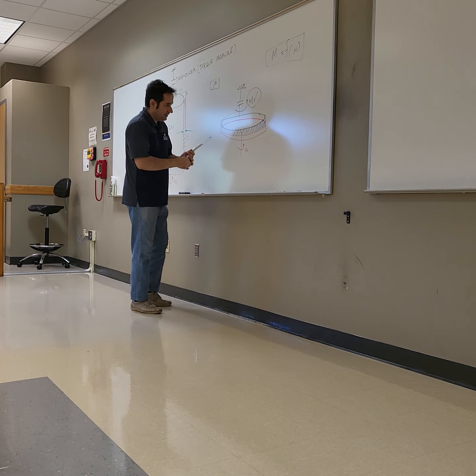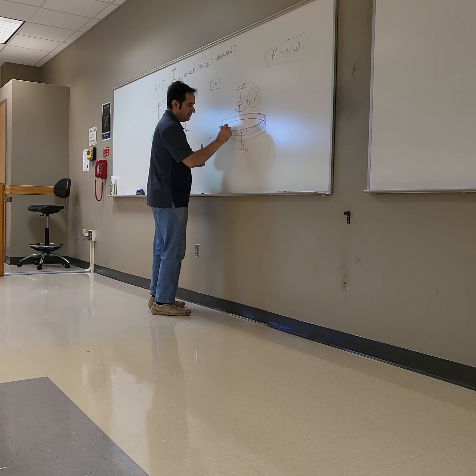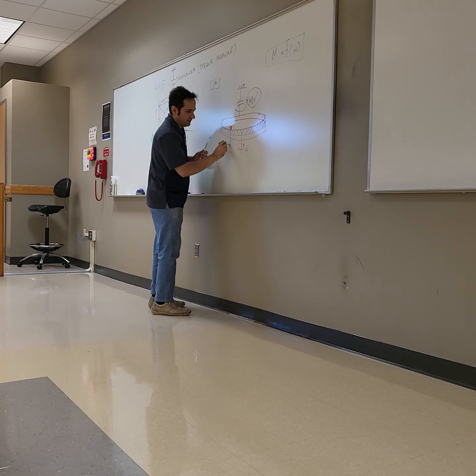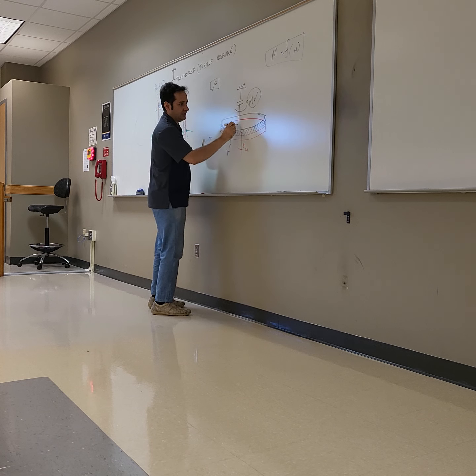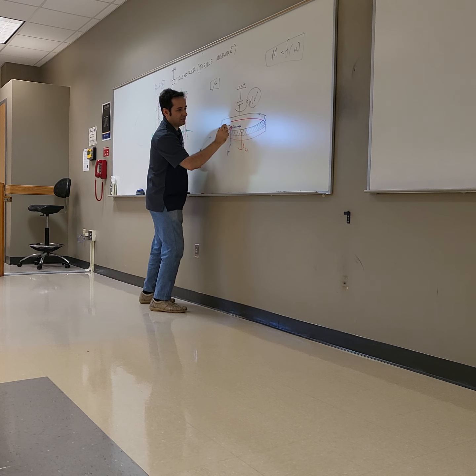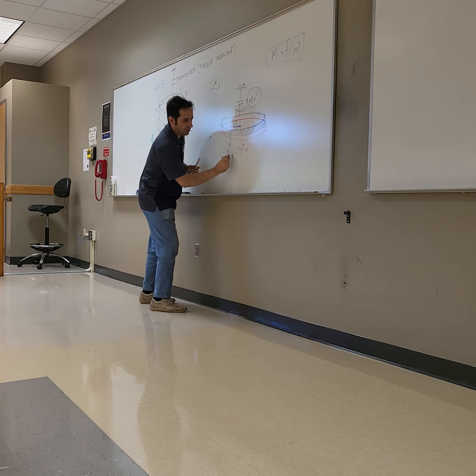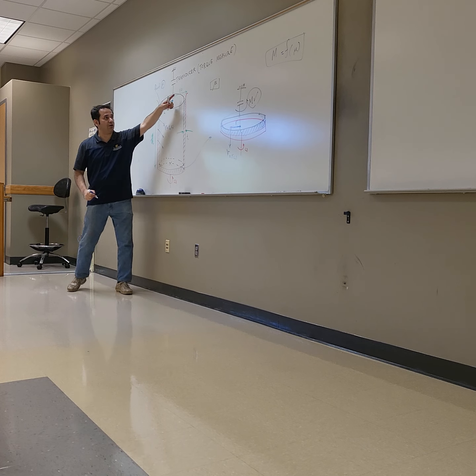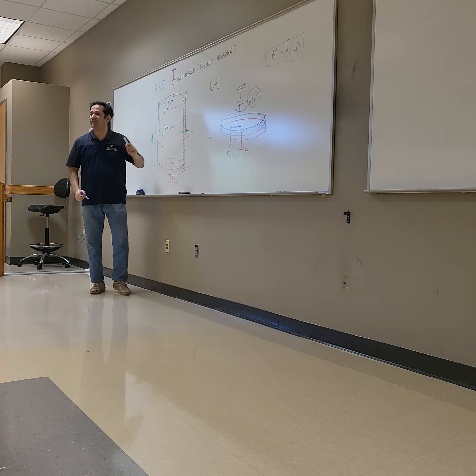But look at here. Every fluid element in contact with this disk, any element you pick, when you rotate, you have a velocity vector V. If this is the center, that velocity vector depends on the radius. This is r, so it is going to be r omega. It's not R0 omega. So it's variable.